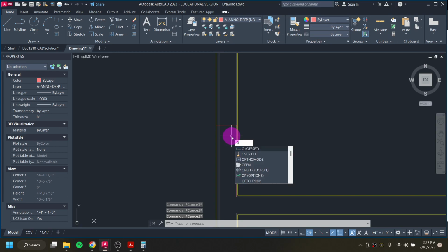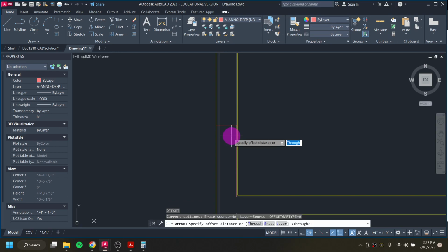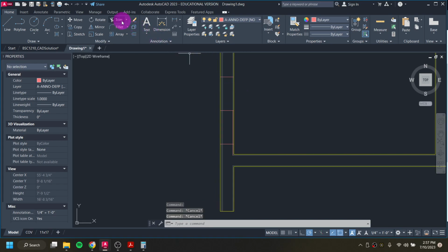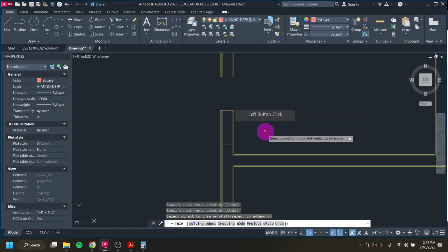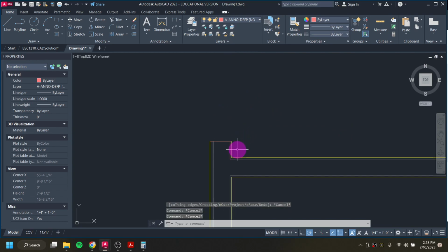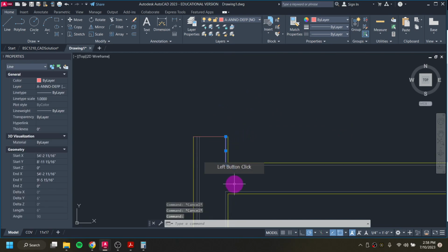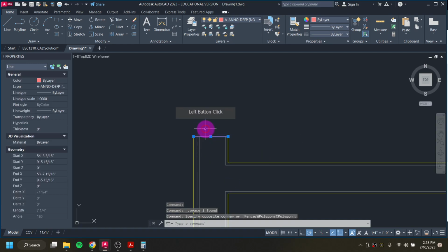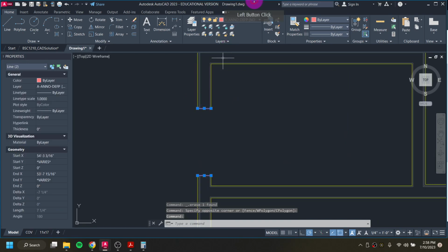And then I'm going to offset, O, enter, for my distance I like through, enter, down 1.5 feet, up 1.5 feet. Now I can trim. So again, that's this button, or TR, slice through, slice through. I can even just click on that to delete it. If I forget to delete this line, as I mentioned, it's no big deal, but I do kind of like going back and erasing them.